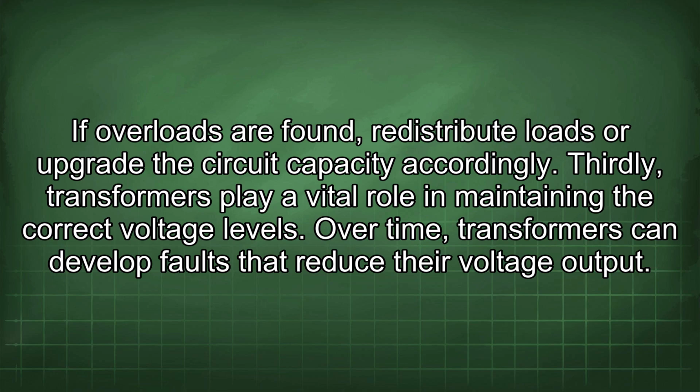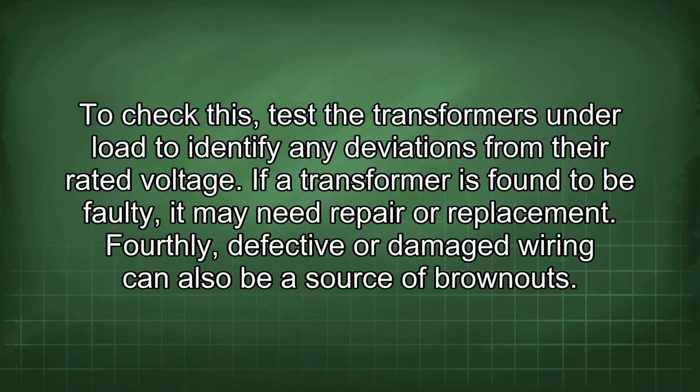Thirdly, transformers play a vital role in maintaining the correct voltage levels. Over time, transformers can develop faults that reduce their voltage output. To check this, test the transformers under load to identify any deviations from their rated voltage. If a transformer is found to be faulty, it may need repair or replacement.